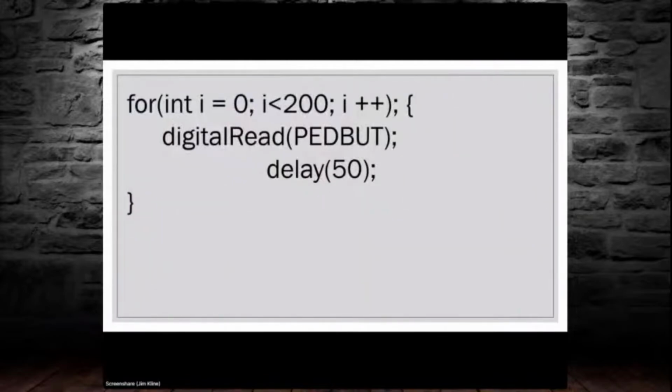Using a for loop allows the sketch to constantly check the status of the button approximately every 50 milliseconds. Different delays can be used other than 50. The for loop runs in place, so to speak. It works by making successive passes, and another way to think of it is as a step counter that increments by 1 on each pass.